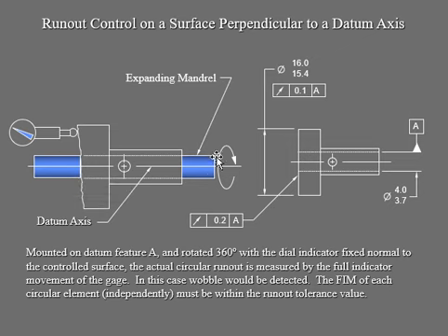You're mounted on this datum feature A, which is your axis, your surface. We're going to verify by using this dial indicator. If you have a wobble, then your material is going to be more on one side than the other, and of course your perpendicularity is not going to be perfect. It will be off. That's what it's saying.